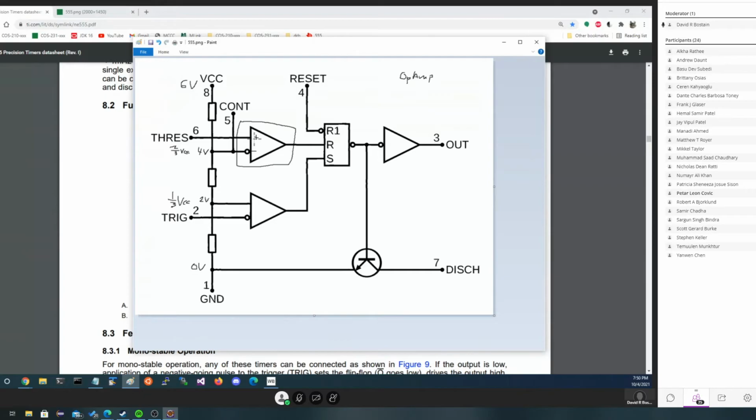Now, normally an operational amplifier is operated with what we call feedback, meaning a piece of the output is brought back to the beginning to make the math a little bit more scaled into a value. In our case, we have no feedback. I'm just going to write no FB. Because there's no feedback, we're operating as something called a comparator. It's one of the ways it can operate. Comparator.